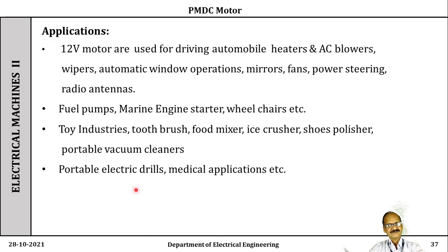As its field circuit is continuously on, irrespective of whether the motor is working or not, such motors are totally enclosed to avoid collecting magnetic junk from the neighborhood of it. Thereby the magnet can become weak also. Another factor is, as the motors are permanently enclosed, there will be more temperature rise. However, there will be no such temperature rise issue if such motors are used for a short period or a short duty.